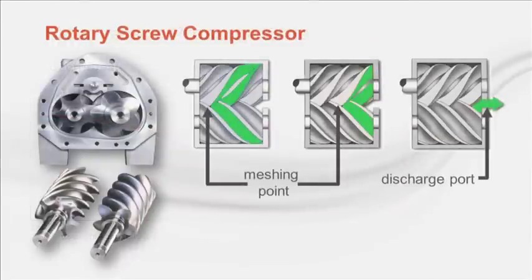Many people may not be familiar with how a helical rotary screw compressor works. Viewing the compressor from the top shows that after the pockets of refrigerant travel through the intake area, the vapor is confined within pockets created by two helical rotors, one of which is driven by the motor. The continued rotation of the meshed rotor lobes causes the meshing point to travel through the discharge end of the compressor, driving the trapped refrigerant vapor ahead of it. This action progressively reduces the volume of pockets compressing the refrigerant. The compressed gas is then pushed out the discharge ports.